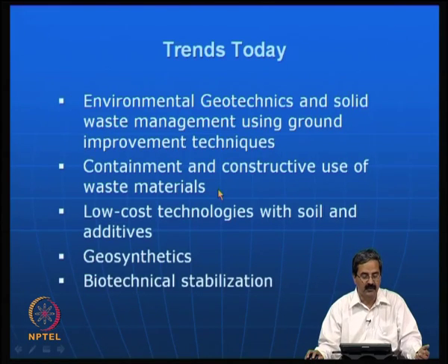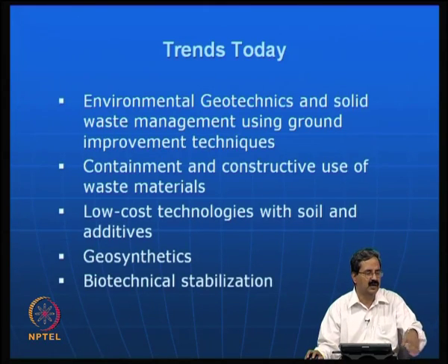And the other one is, so much waste is generated, for example, as I just mentioned, plastic waste, construction waste, particularly for road making. One can reuse some of these materials in some sense. You may not get a 100% benefit out of it, but for example, national highway road waste can be used in a nearby village road, right. You have a big national highway and they thought that resurfacing is required or some more treatment is required, or it should be totally relaid. In such cases what should be done? You can remove the total material, and there are so many techniques to recycle the waste, because recycling itself is an art.